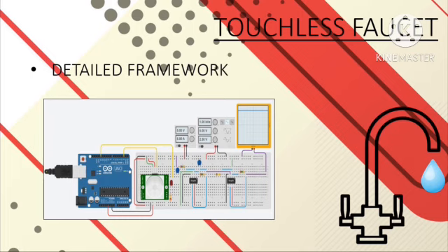The band pass filter will remove the unwanted noise, and it will remove the low and high signals. In this band pass filter, we have 2 capacitors, 2 resistors, and 1 op-amp. Next, the output from the band pass filter will go to the non-inverting amplifier. In the amplifier, we have 2 resistors and 1 op-amp. The non-inverting amplifier will improve the signal to a readable signal for other instruments. The output from the amplifier will go to the oscilloscope.